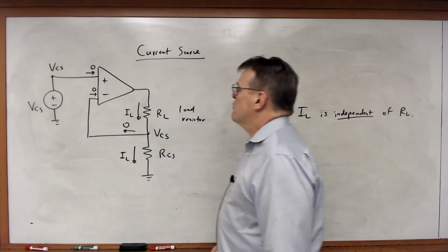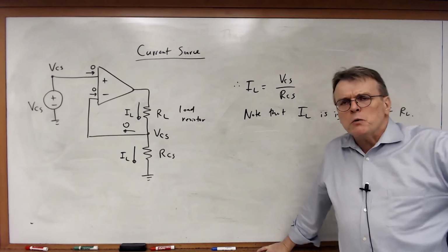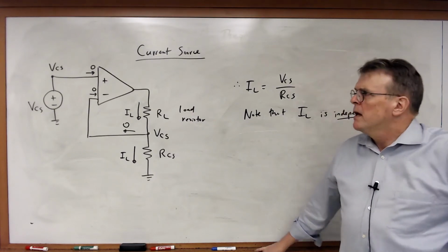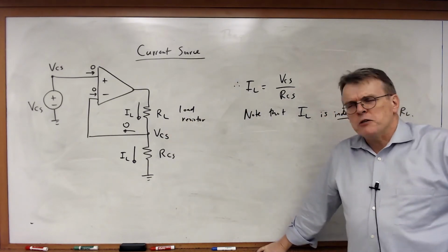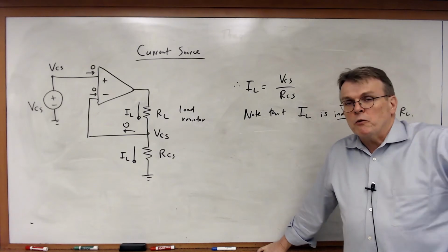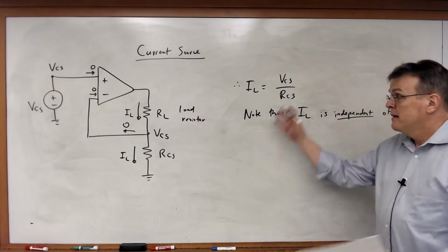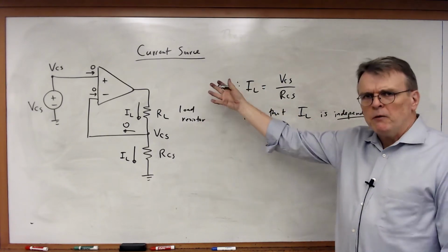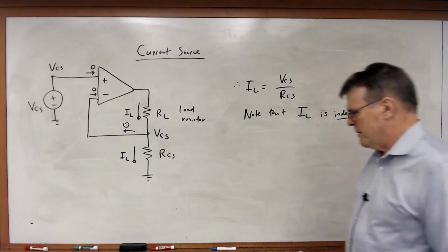Usually people kind of have trouble thinking, how would you make a current source with real circuits? Voltage sources are easy. Batteries, you can think of a battery as a voltage source. But a current source, well, you can do something like that. Create something that generates a constant current through a resistance of any value. You can do it with op-amps. So, one interesting example, and there are lots of different variations on how to build current source circuits like this. Let's look at another interesting circuit.